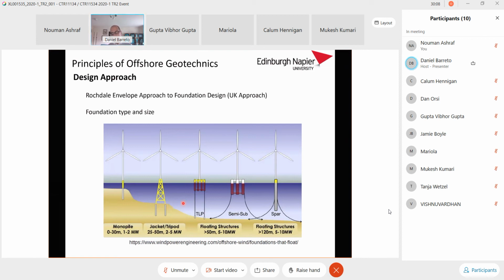If you continue to go down, you may have what we call the tension leg platform, which is essentially a floating structure supported by tension cables, which are then anchored or joined to smaller piles of different types, which are also discussed qualitatively with some detail in the lecture. But if you go deeper, you have more catenary style risers that are anchored to the seafloor via different anchor types, which are also shown in the lecture.